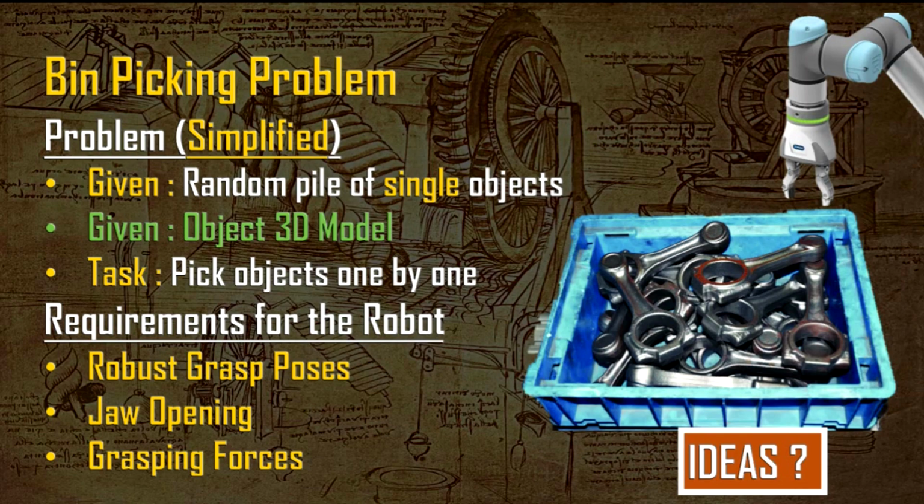Yes, the camera is mounted on the robot. And at first, the robot is at some distance, let's assume something like half a meter. And since the camera catches a full circle, we can measure the diameter of the circle. And we have as a condition, for example, the diameter of the circle from a certain known distance, so we can compare what we measure with the initial information, and in this manner calculate exactly the distance between the detail and the camera. Okay, okay.